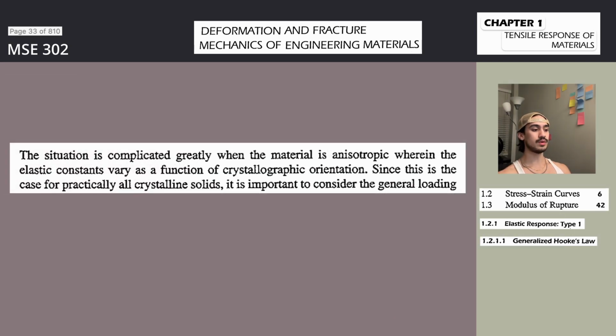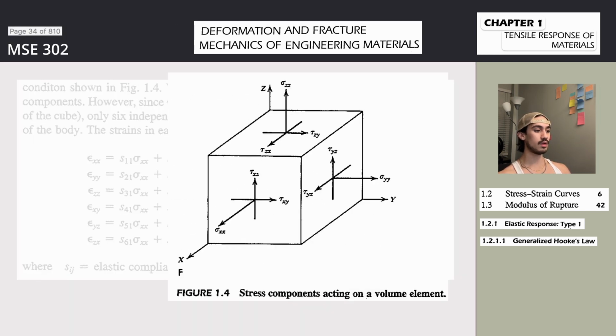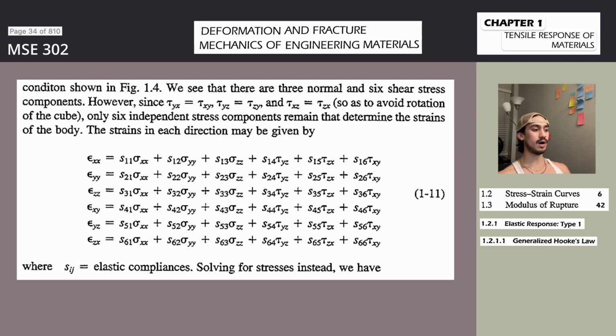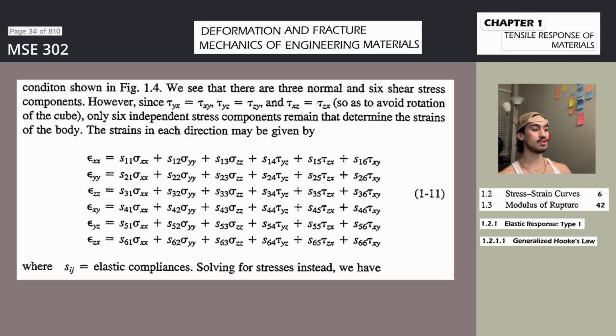Such data may be derived by plotting true stress and associated true strain values on log-log paper. If Equation 1-20 was absolutely correct, a straight line would result with a slope equal to n. However, this is found not always to be the case, and reflects the fact that this relationship is only an empirical approximation. When a nonlinear log-log plot does result from a given material, the strain hardening coefficient is often defined at a particular strain value. In general, n increases with decreasing strength level and with decreasing mobility of certain dislocations in the crystalline lattice. More will be said about this material property in Chapter 3.